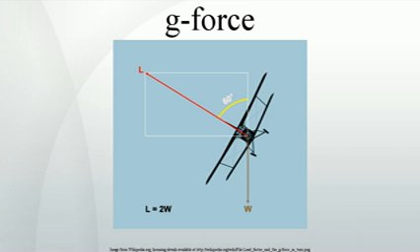For example, an acceleration of 1 g equates to a rate of change in velocity of approximately 35 km per hour, 22 miles per hour, for each second that elapses. Therefore, if an automobile is capable of braking at 1 g and is traveling at 35 km per hour, 22 miles per hour, it can brake to a standstill in 1 second and the driver will experience a deceleration of 1 g. The automobile traveling at 3 times this speed, 105 km per hour, 65 miles per hour, can brake to a standstill in 3 seconds.